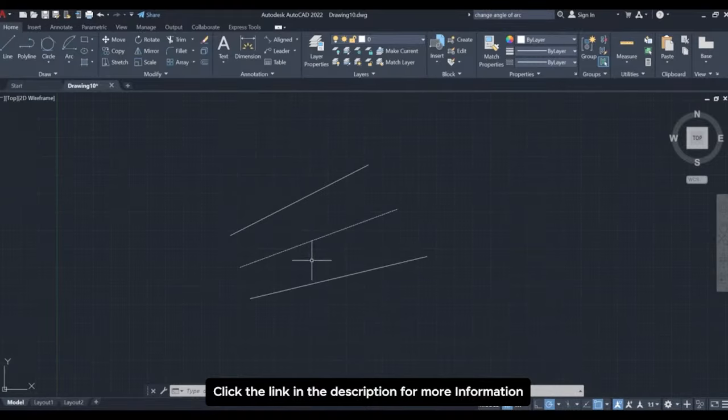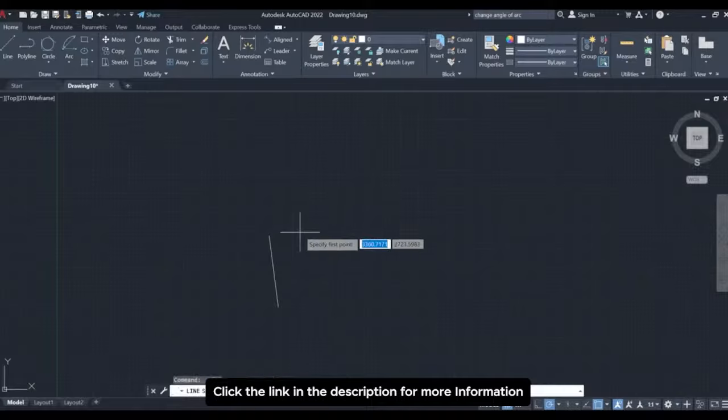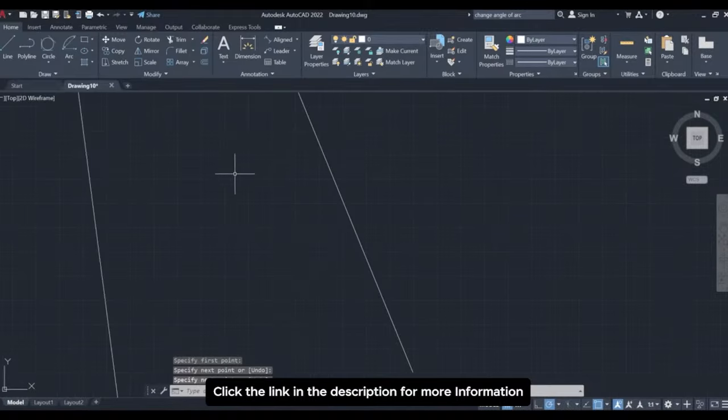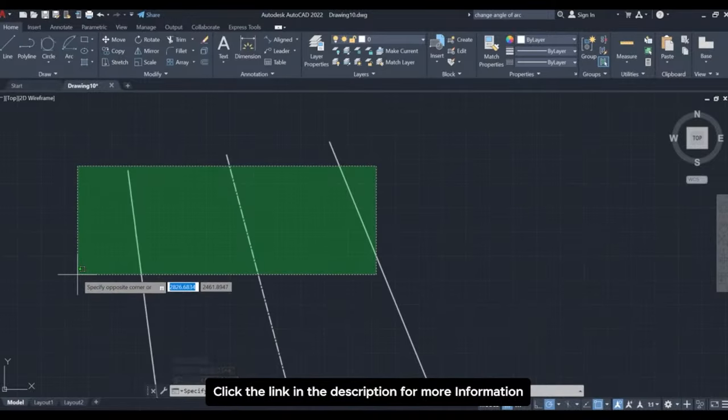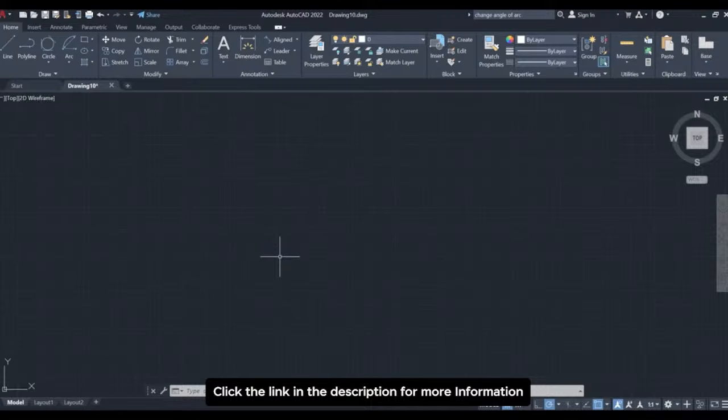It very simply helps you create centerlines between two separate lines to represent any kind of centrally passing object or anything like that. So once again, that's CL for centerline. Select the first line, the second line, and automatically a centerline will be created between those two lines. That's the centerline command. So we are yet to discuss rectangles, ellipse, splines, polygons, polylines, as well as points.